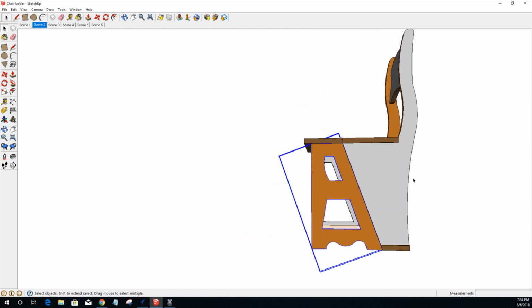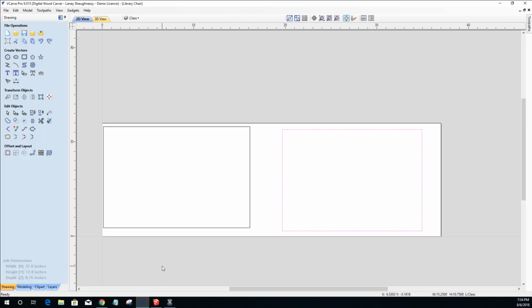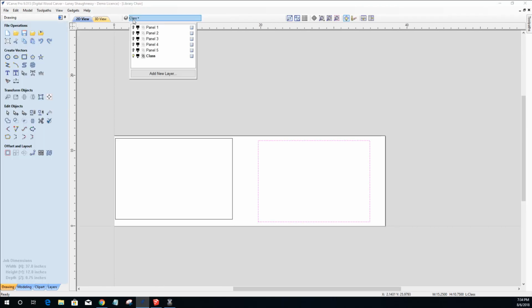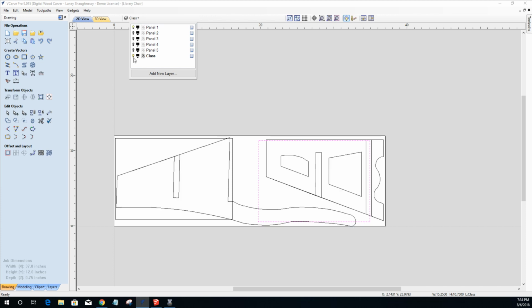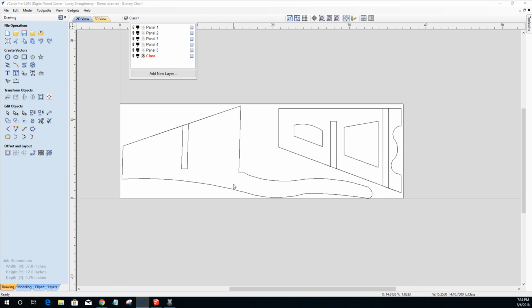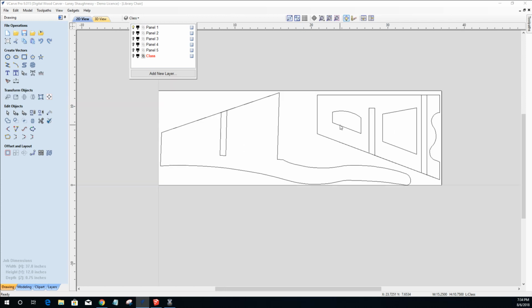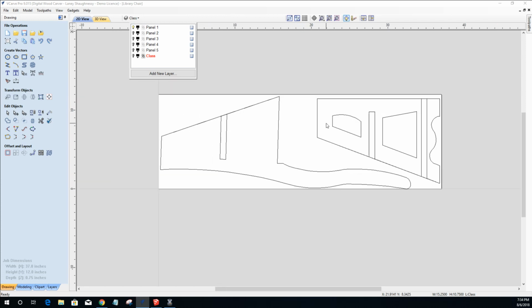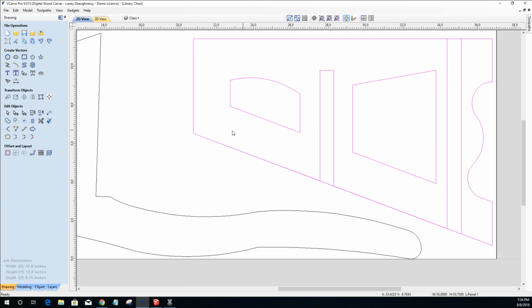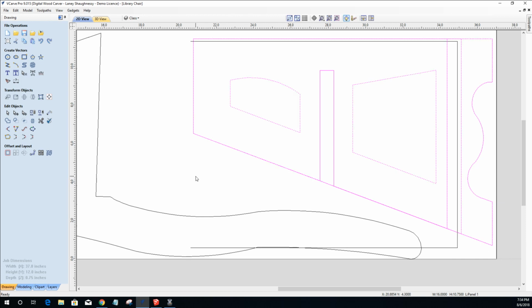And now that we have the skeleton, which I'm providing all the files, DXFs and everything to you for, now we can go into the Vectric software, and we can look at those parts laid out, and now we could really just start customizing and changing up anything that we want. Now it's important that if we are going to do some kind of cut through, let's explode these parts out, ungroup them, should I say, not explode.